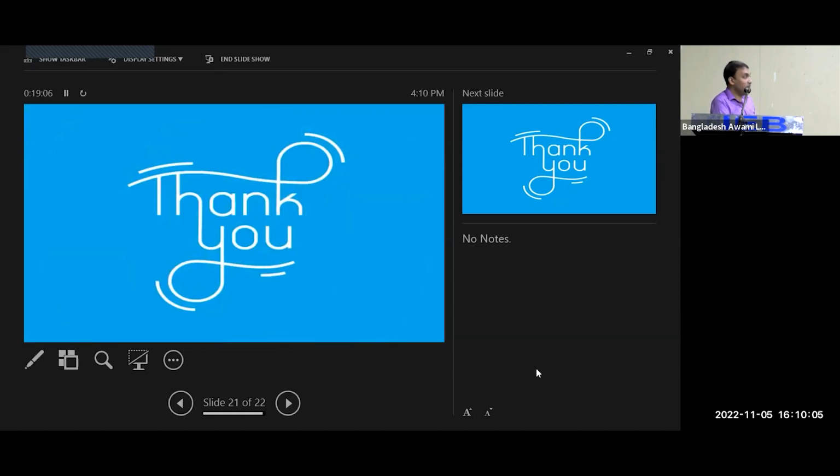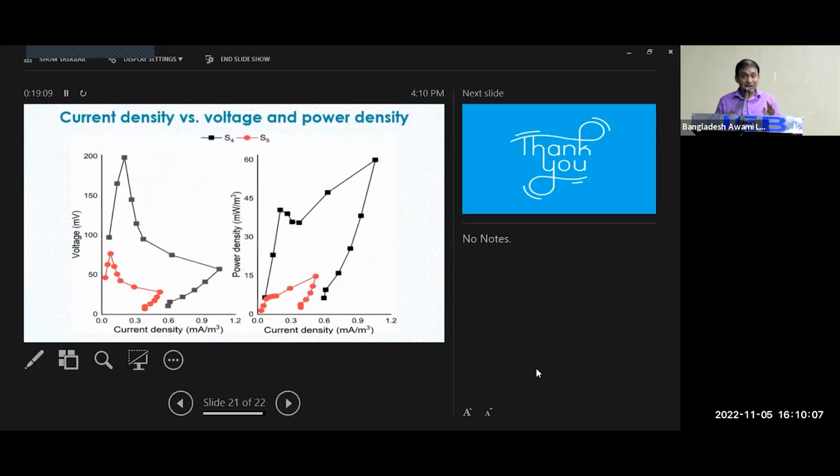But our main conclusion is we can use this constructed wetland system, whether you integrate electrodes or you do not integrate electrodes. You can simply use a planted system, follow some simple schedule, 2 days or 3 days dosing followed by a 4 day resting period, and you can manage the sludge. So we have provided the solution to WASA, and now it's up to them what they will do. Thank you very much.